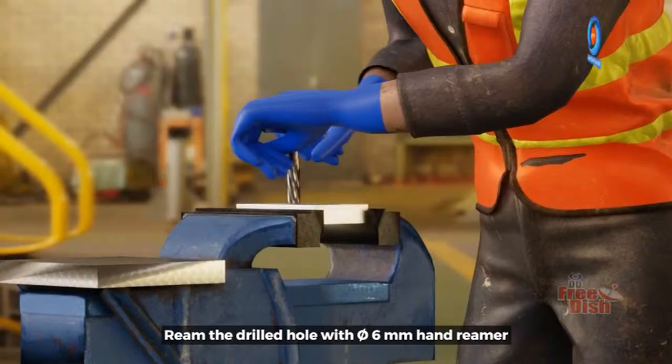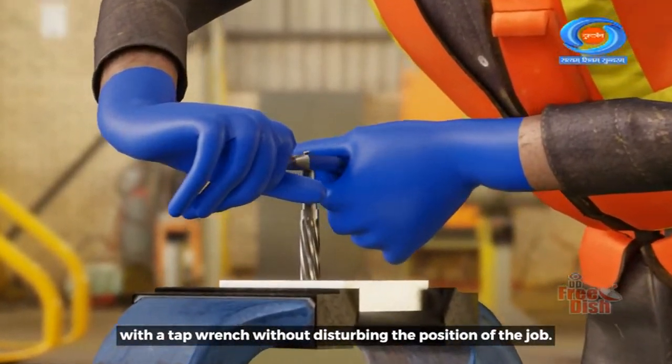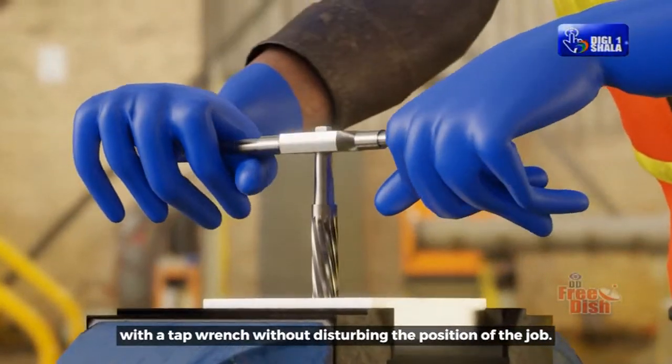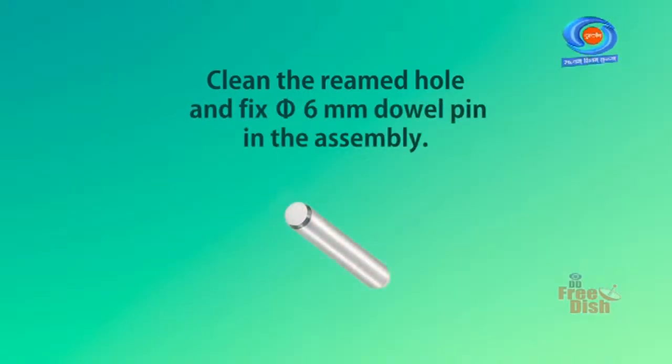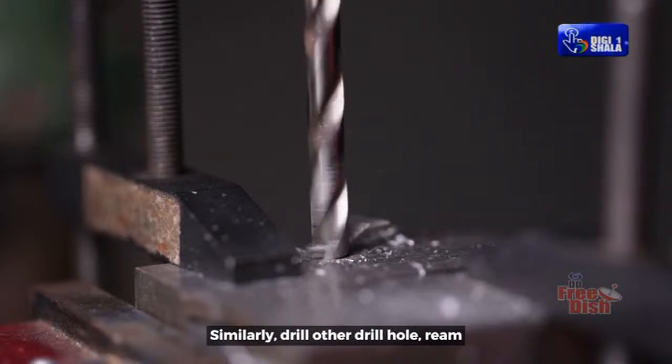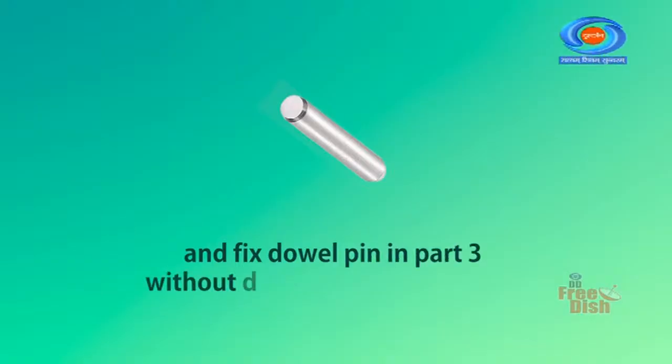Ream the drilled hole with a diameter 6 mm hand reamer with a tap wrench without disturbing the position of the job. Clean the reamed hole and fix diameter 6 mm dowel pin in the assembly. Similarly, drill the other hole, ream and fix dowel pin in part 3 without disturbing the assembly.